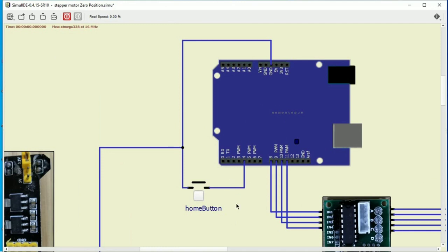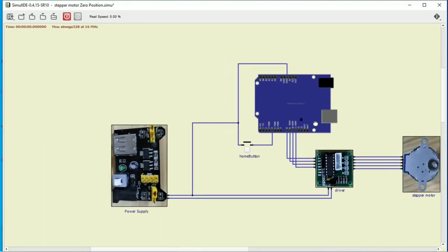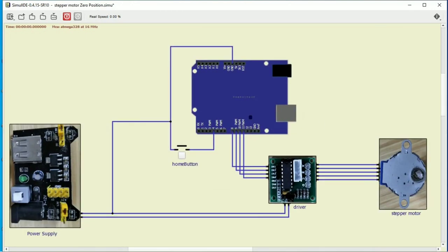So you do not need to connect it with a resistor because it will be using an internal resistor of the Arduino, and your Arduino here will go to the computer. Alright guys, I think that's all for this circuit, and let's go to our sketch now.